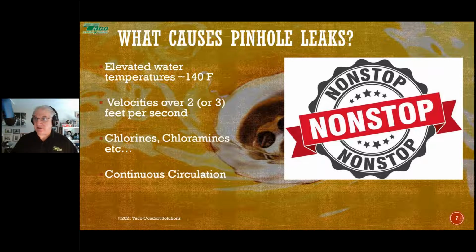Now, here's the thing. Having the pump running continuously is wicked easy, right? That's the easiest control strategy there is. You plug it in, you get the heck out of the way. Hey, I've solved a bunch of problems. Number one, I don't have to pay for it. I don't have to buy any kind of a control strategy or do anything for my control strategy. Number two is any time of day or night, 24/7, if anybody opens up a hot water faucet, they're going to have hot water, right? So that solves a problem, and it meets a customer expectation.